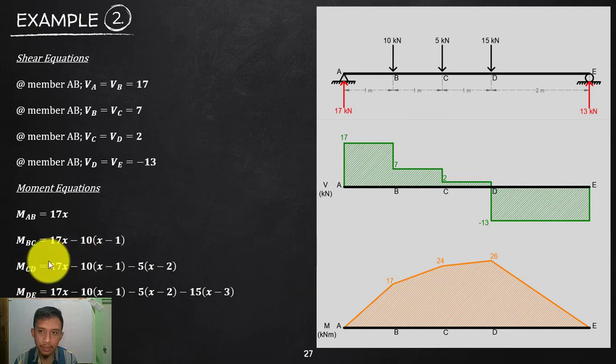And then substitute in the equation you established at CD your 2.5, and you will end up with the value of the moment. Or, if you are using the diagram, all you need to do is plot that 2.5, get the equivalent shear, which will still give us 2. And then if you want the moment, plot your 2.5, and you will have the moment here between 24 and 26. You can check that one. What you get using this equation and using your diagram should be the same.